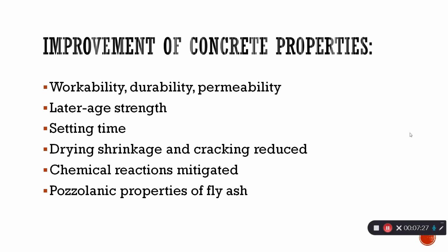Results of using fly ash were that workability and mechanical strength were improved when there was up to 50% replacement of fly ash in a self-compacting geopolymer concrete binder. Fly ash, because of its pozzolanic properties, contributes to improved flow characteristics and a dense microstructure in the ultra-high performance concrete, UHPC. When replacing cement with fly ash in UHPC, a range of 20 to 30% is ideal for replacement. The carbon footprint for UHPC is reduced when replacing cement with fly ash. Strength over time will be increased in UHPC with increased fly ash dosages.